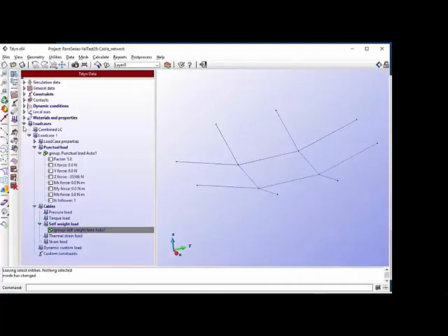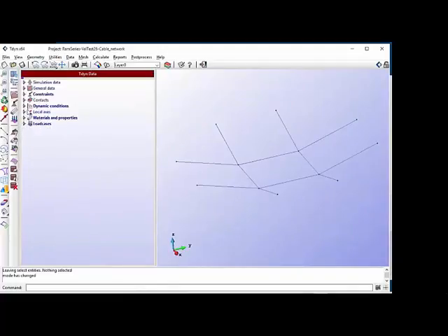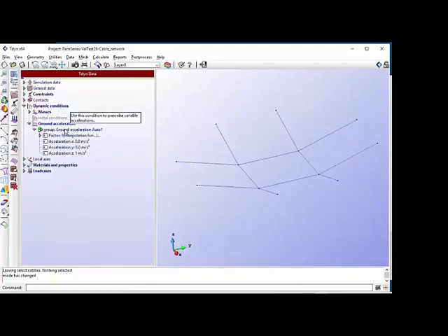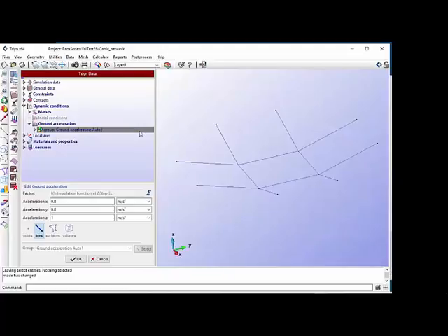And of course, the important load in this case, which is the time depending load corresponding to the earthquake. This is interesting because it's not applied as a usual load, but applied to the whole of the structure as a ground acceleration. And the exact signal of the real earthquake, which was measured, is applied to the structure. So it's a vertical acceleration with the following time history.